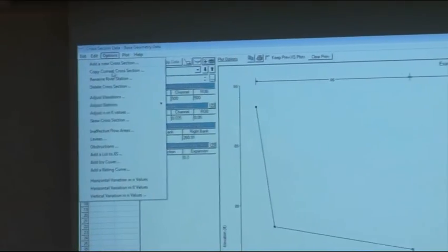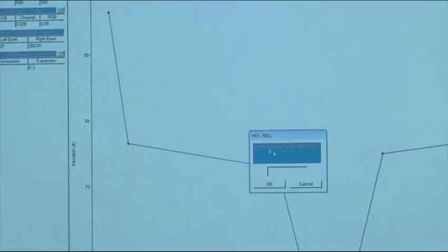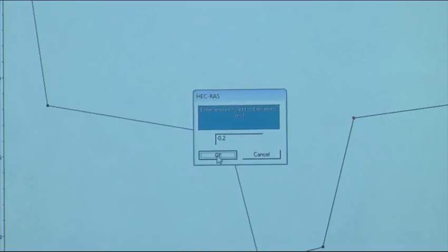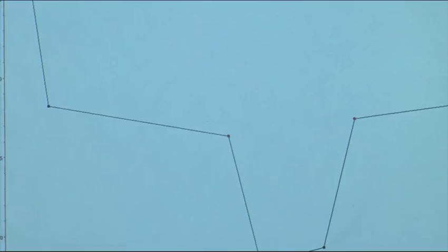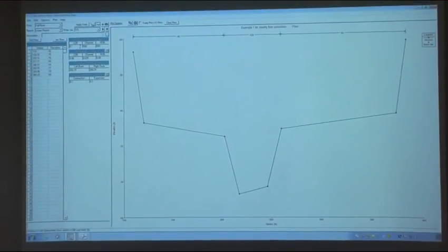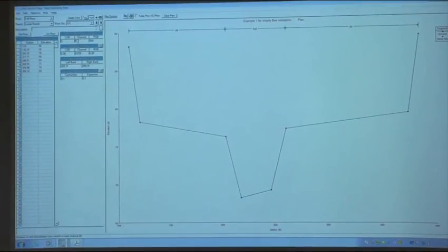Then the last one, copy the current cross-section. We enter the cross-section 9.5 and go to the options, adjust elevation as minus 0.2. And no change on adjust stations. Since this is the last cross-section, we have to set the length to be 0 for all three again. So the downstream reach length for all three paths will be set as 0 again. Then you can apply the data.